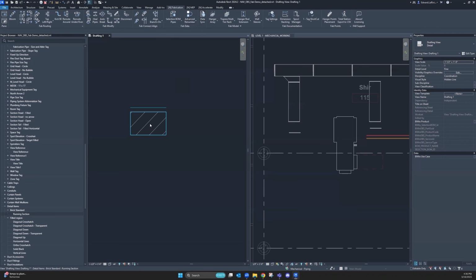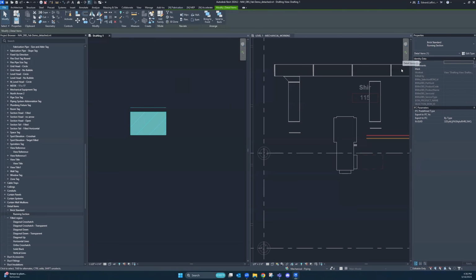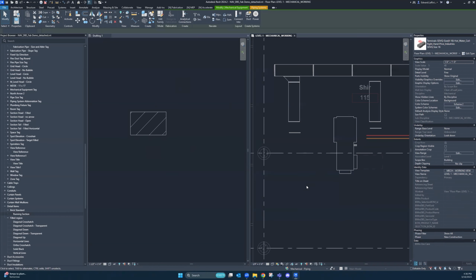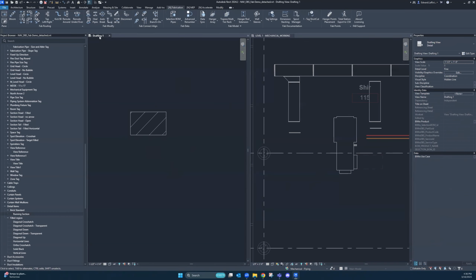The intent behind Data Sync is to allow us to grab a detail item and link that detail item to a Revit family, a piece of information inside Revit, so that the data tracks between the two of them. Detail items are often used in those drafting views, so this is a way that we can have data maintained across multiple elements without siloing that data. So opening up Data Sync, we'll see we have a few options inside here.